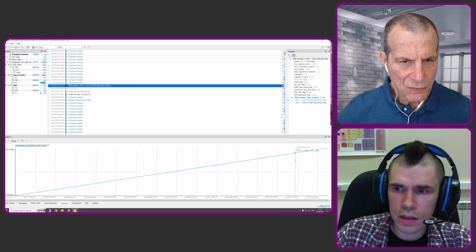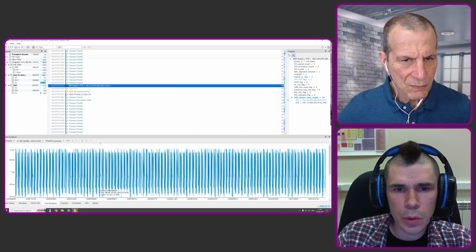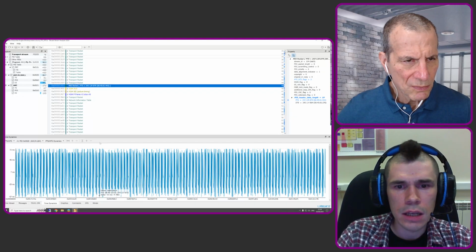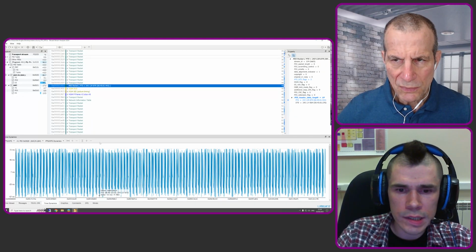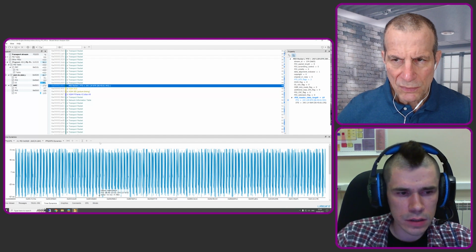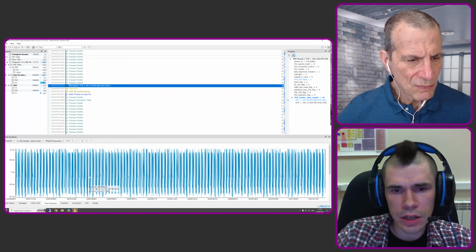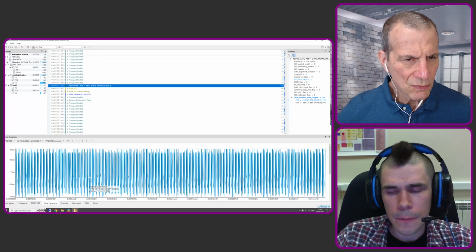At least we think so, and we don't have errors in TR101290. But if we check the PTS and DTS timestamps, we see negative deltas between them. Usually they should be linear, they should be constant.